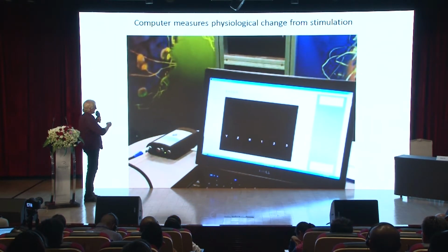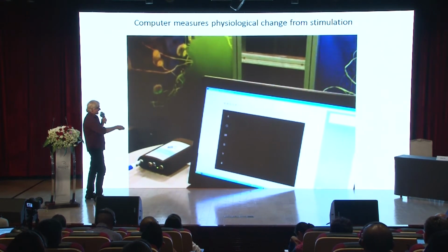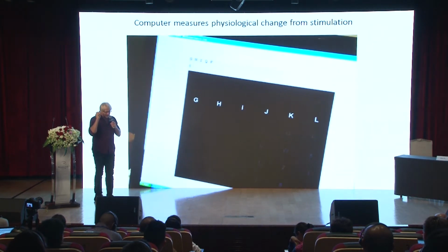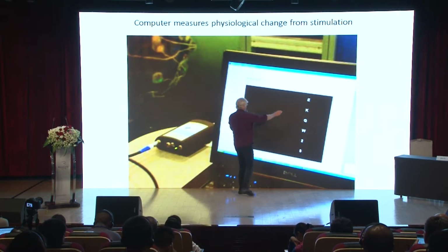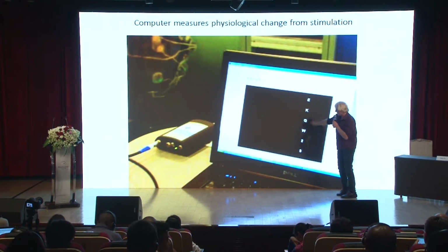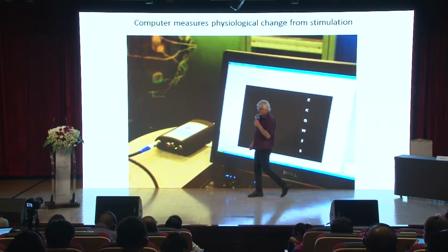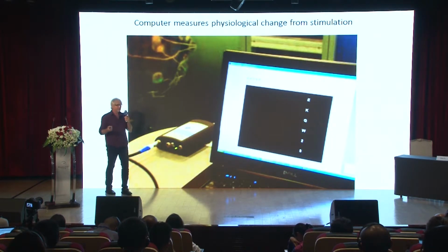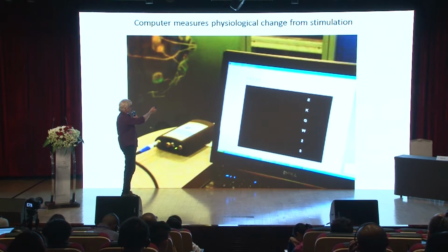This is one way an interface can work that senses physiologic data, and it shows an evolution of how this could work. Measurements are being performed on the brain, and this individual is looking at the screen, and different letters are flashing on the screen. Say the person's thinking of the letter W. When the row with the W is presented, and the person's looking at the W, there's a signal in the back of their brain, a lighting in the brain, and when the column comes up with the W, their brain also lights up. It's called the P300. Because that one lights up and that one lights up, they know exactly where the person is looking. And so it can convert this brain perception into an actual physical result.